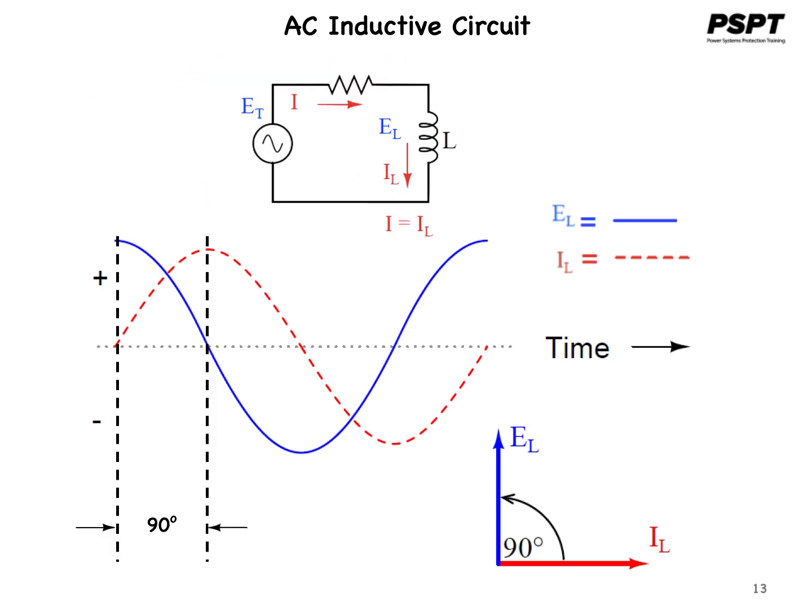An inductor's opposition to change in current translates to an opposition to alternating current in general, which is, by definition, sinusoidal and always changing in instantaneous magnitude and direction. This opposition to alternating current is similar to resistance, but different in that it always results in a 90-degree phase shift between the current and the voltage. Because of the differences, it has a different name: reactance.